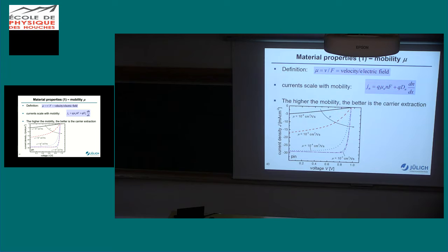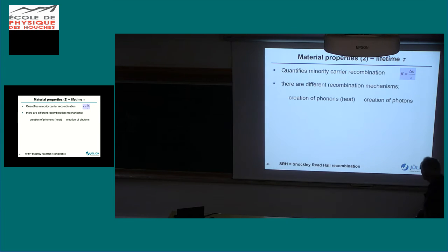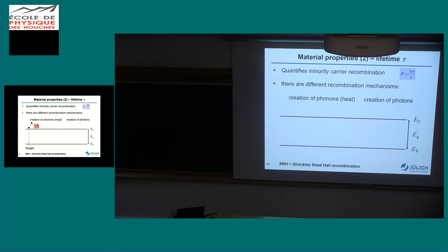By the way, that's not saying that any charge carrier inside the absorber knows, oh, I'm the drift guy, I follow the field, and the other one says, okay, I'm the diffusion guy running around very wildly. That's not the case, it's just a mathematical separation into these two terms, to avoid misunderstandings. But there is a mobility here, and hidden in the diffusion constant is also the mobility.